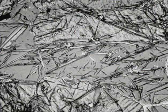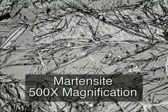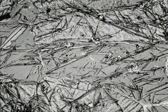It gets trapped inside the space lattice as the austenite transforms, resulting in a distorted, body-centered lattice called martensite. Martensite has an acicular or needle-like structure. Martensite is very hard and very brittle, and the higher the carbon content, the harder and more brittle it becomes. The rapid cooling that causes martensite is called quenching.